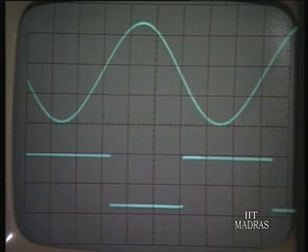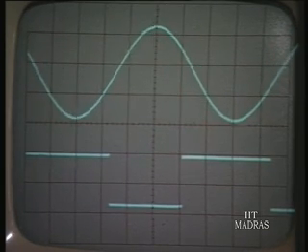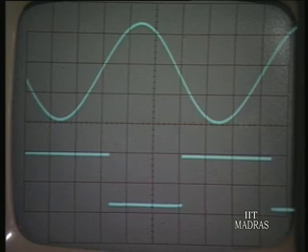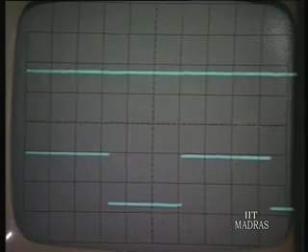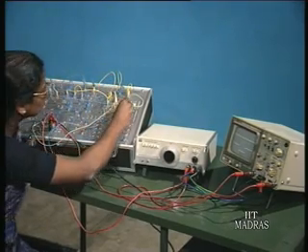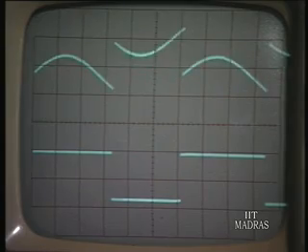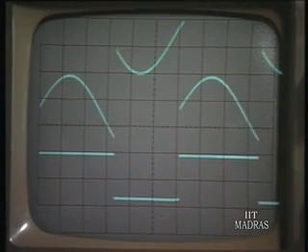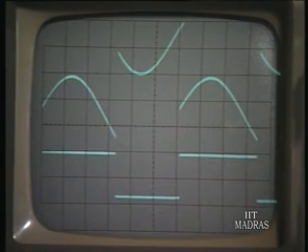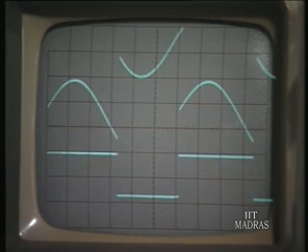See, it rapidly falls. Again tune it, exactly, tune it exactly to the center frequency so that you get the highest fundamental output. Now let us show you the notch output. The fundamental has been eliminated, so only the harmonics should be there. Their output amplitude should be extremely small, and therefore she is changing the scale so that the small amplitude of the harmonic content can be shown to you at the output of the notch, and you can see that waveform exactly as I had shown you on the board.